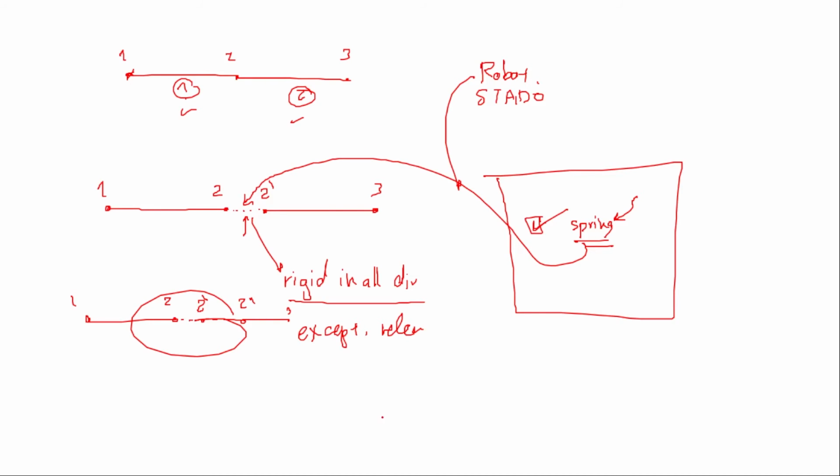In other words, softwares trick you by saying, well, this is node number 1, node number 2, element number 1, and they add an extra node for the release, and then they add node number 3. This is element number 3, and this is special element number 2, and this is special element number 3, which contains a special stiffness matrix where everything has high values with exception to what you release. What you release is going to have a 0.001 stiffness value.